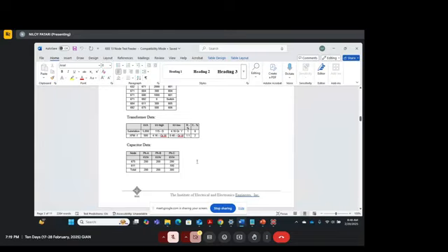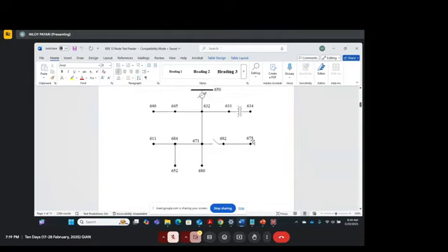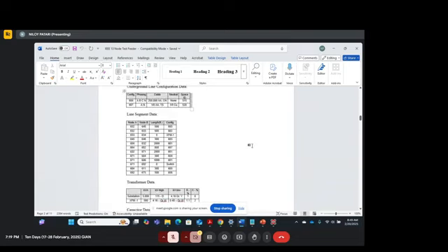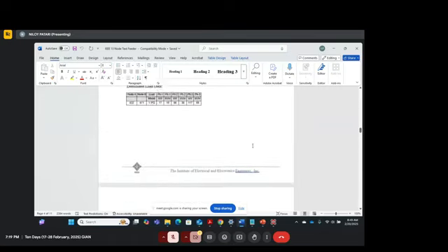So 675 and 611 are exactly here, on the right hand side and on the left hand side. Why are these capacitors placed at the periphery of the network? Because at the periphery of the network, you'll have the lowest voltages, right? So when you have low voltages, in order to boost up that voltage, those two capacitors are placed. Now, I'm just giving an example. You can place the capacitor on other positions as well, but just for your clarity.